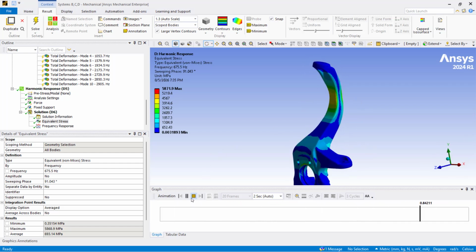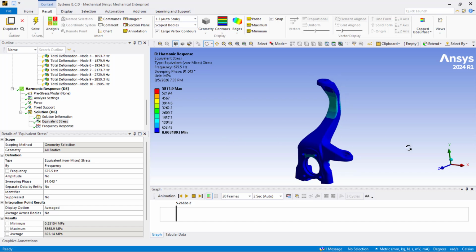Now let's say you have an automotive structure like this. You need to carry out this kind of analysis, then you extract the peak with respect to resonance. It will have a working range of frequency, so 0 to 1000 hertz or 0 to 1500 hertz should not have peaks.